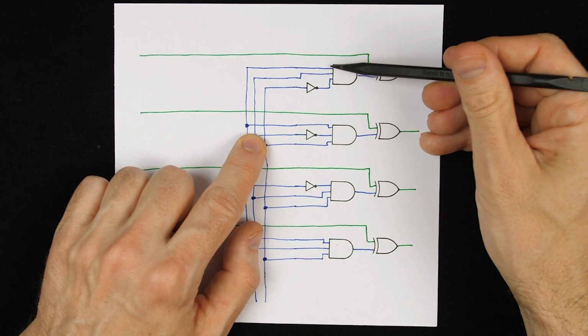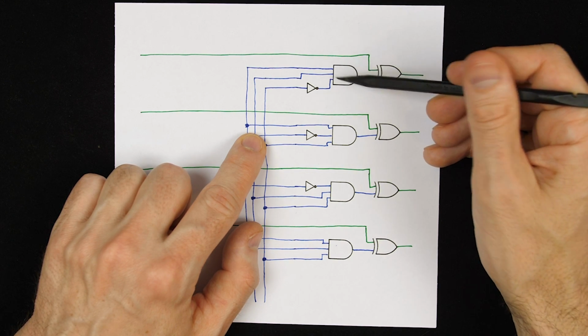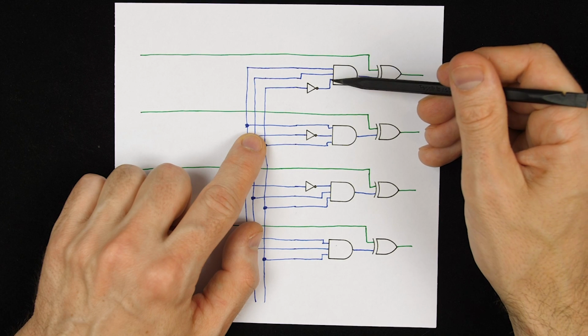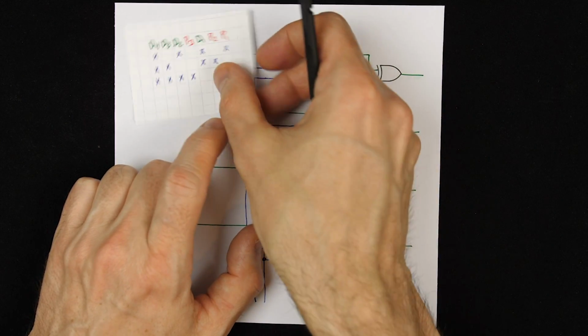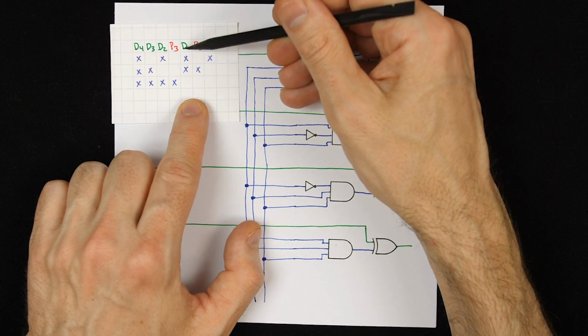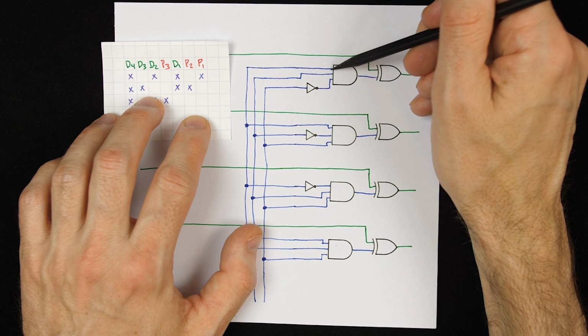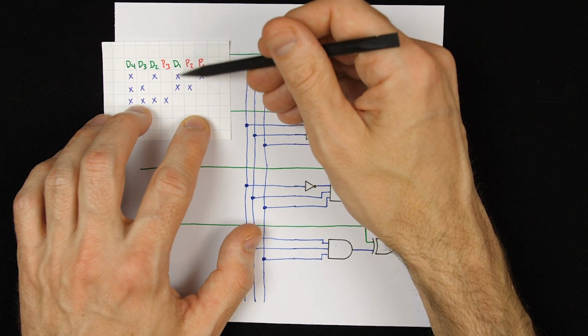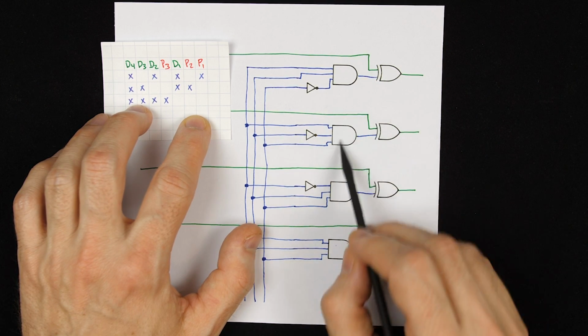So in this case, we're selecting the value 1, 1, 0. Or actually, I think it's the other way around. I think it's 0, 1, 1. Yeah, so 0, 1, 1, which is a binary 3. And so that's actually going to select that first bit position, right? So if we have a 3 coming in here, so 0, 1, 1, that means that we have an error in the third bit position, which is D1, and we want to flip D1.